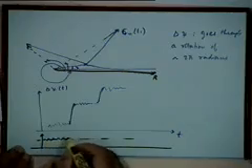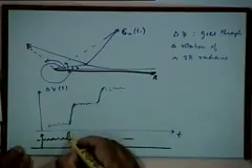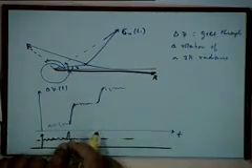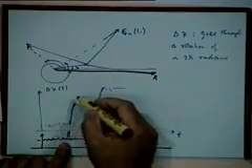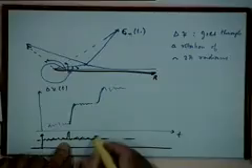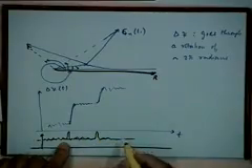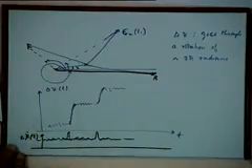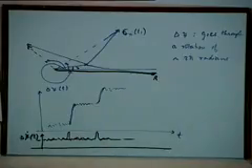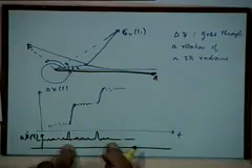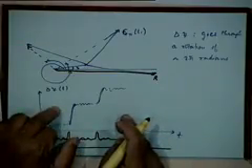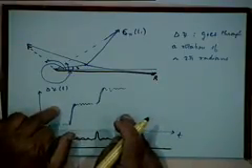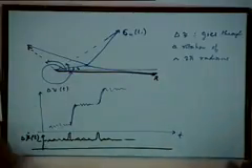version of this, right? So you will see some fluctuations, and corresponding to this you will get a pulse, the derivative of this step function. Similarly, you will see something like that. Okay, so this is delta psi dot t, the derivative of this. This is what it will look like. So FM demodulator output will look like this, phase demodulator output will look like this, right? And now how does it make a difference to the noise power output?